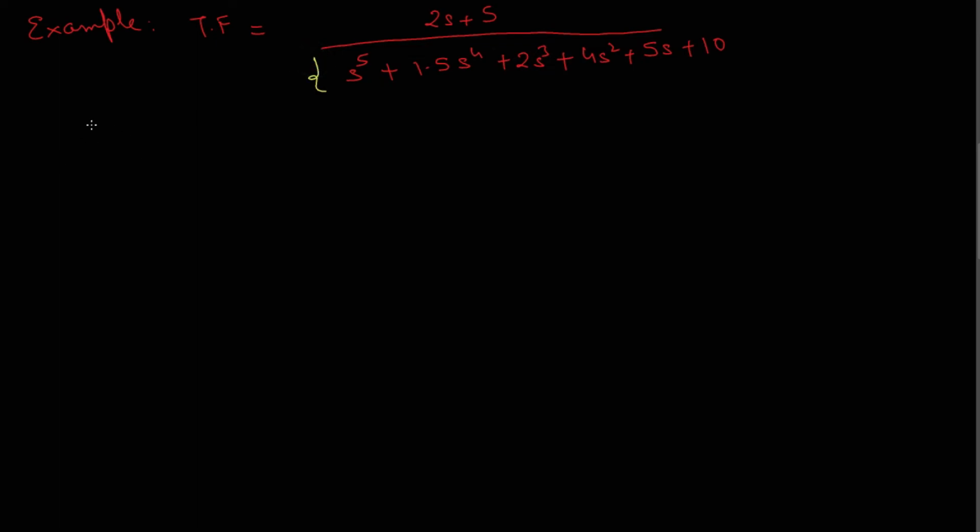To understand the operation more clearly, let's take an example and perform these operations. Now here you can see the transfer function and we will take the denominator of this transfer function as the characteristic equation. Here we can see that none of the previous criteria which we mentioned from step 1 to step 3 are satisfied. So we will draw a vertical line, and as you can see the highest power in this characteristic equation is S raised to power 5.